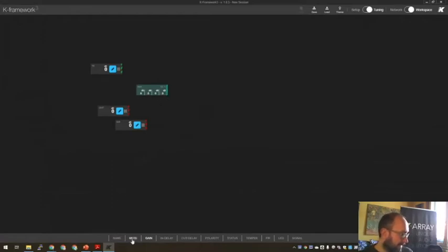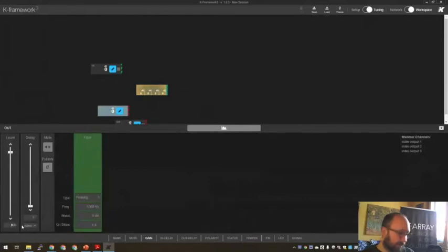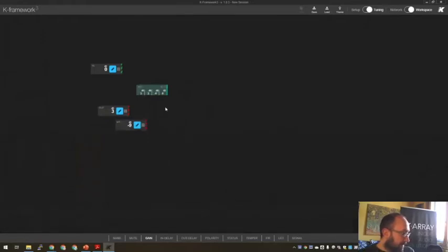So let's do an example on the output. Let's give 3 dB to everything, and then we go to the sub, and we take down 9 dB. I don't like subs. So 3 dB to all the 3 outputs, -9 on the sub, and here I got +3 on the tops, and -6, which is the result on the subwoofer output.